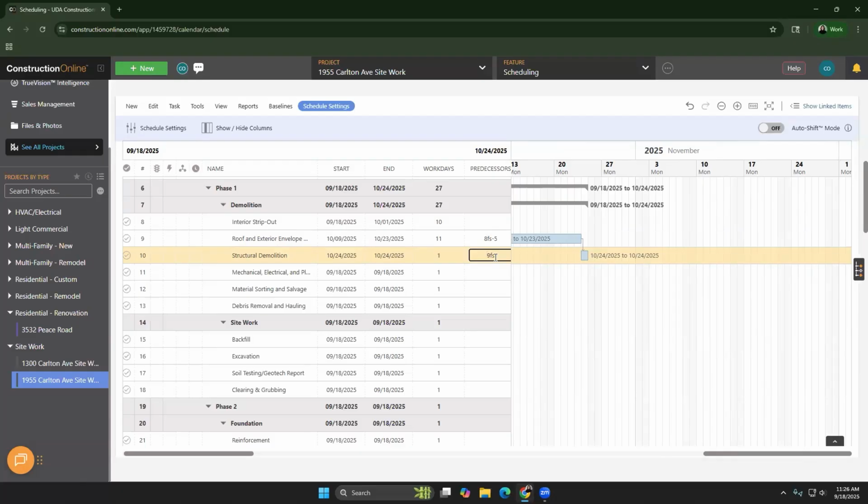But let's say you are on a job site and you want those to be updated as soon as possible. As soon as a task finishes, you want the next one going, boom, boom, boom. All you have to do is, over in the left sidebar, there's this little icon right here. It looks like a little lightning bolt. You can click on that, and that's going to mark that task ASAP. So that means that if this task were to finish early, it's going to go ahead and push that successor forward so that now 10 is going to be updated for 9.